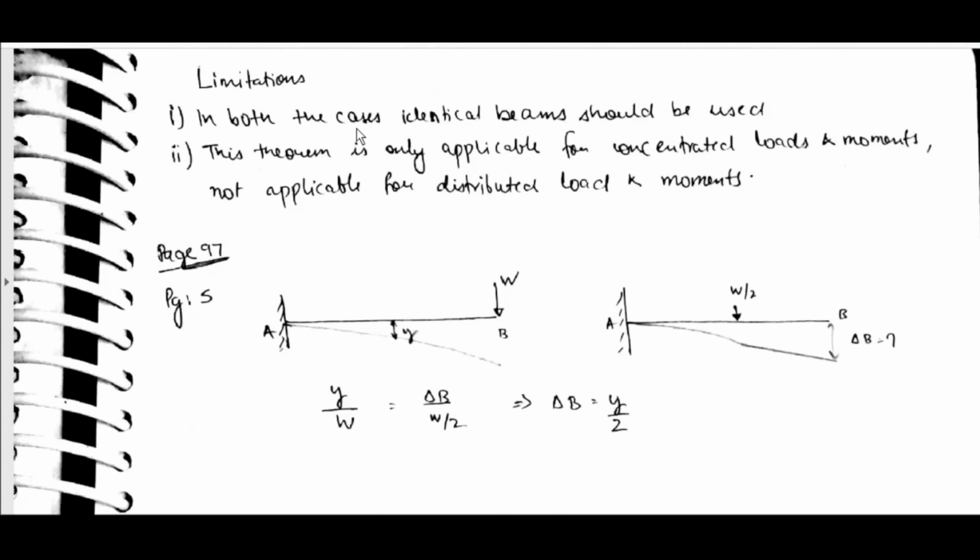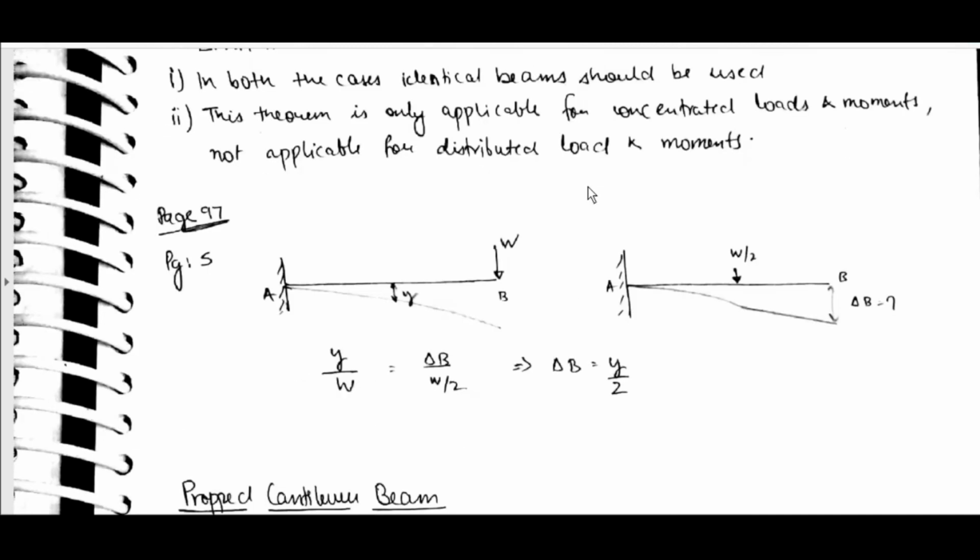Limitation: in both the cases identical beams should be used. This theorem is applicable only for concentrated loads and moments, not applicable for distributed loads and moments.